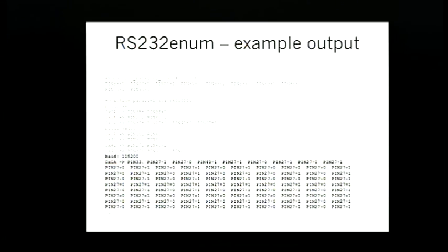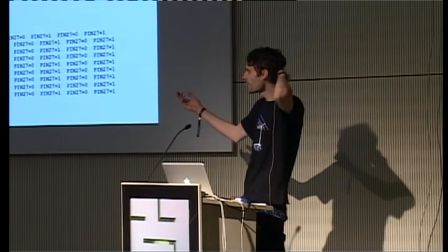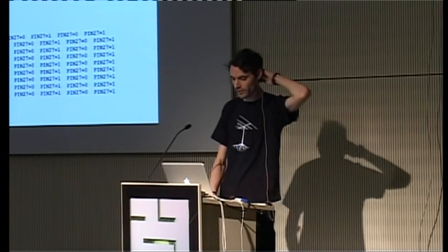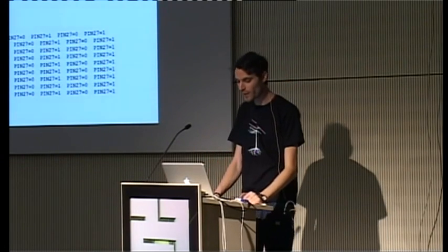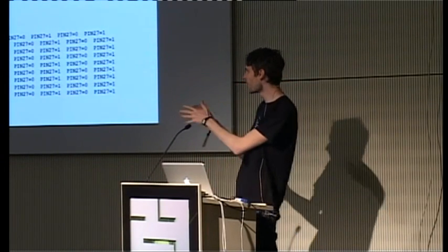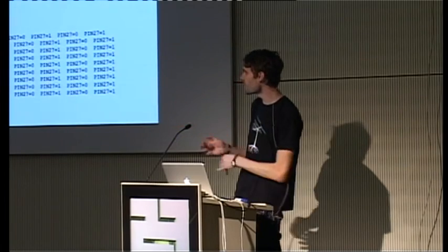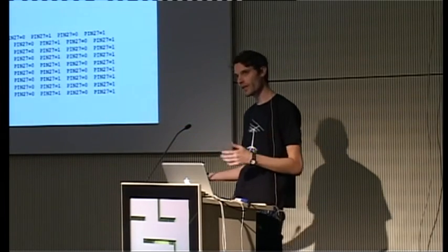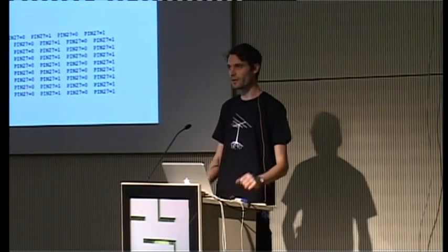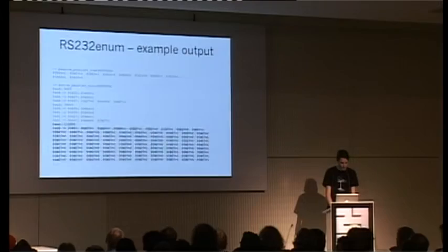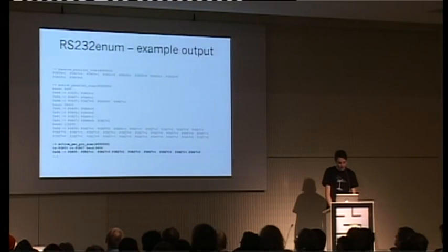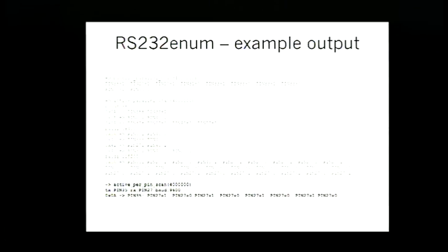In fact, it definitely indicates serial, because the way in which the baud rate is sent is also using serial. So it probably wouldn't respond. Who knows? Anyway, at that point, you would probably take it and plug those pins, pin 27 as your RX and pin 33 as your TX, to a serial cable, and hopefully you'll find serial. It also does another scan, which is active per pin, as opposed to polling the RX pins in parallel. It selects one and pulls each one individually for each combination. So I'm not sure that's useful, but it might be good for debugging.